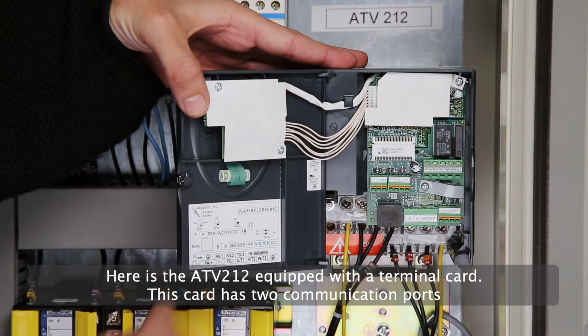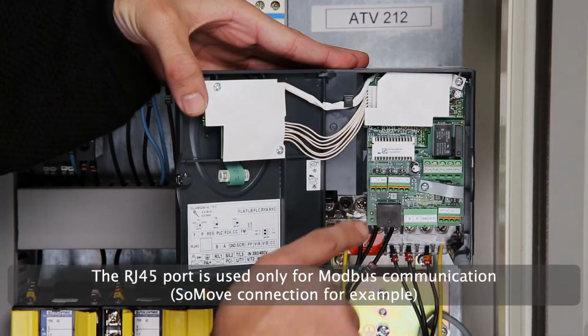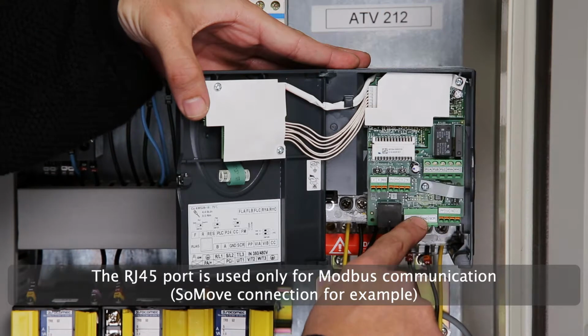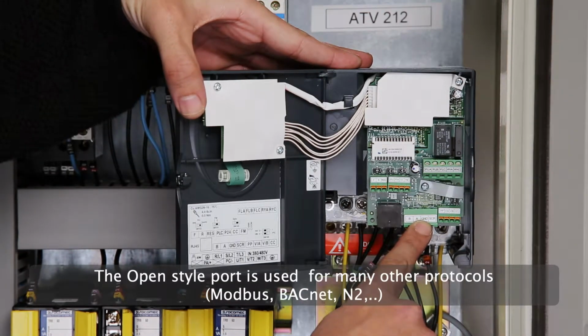Here is the ATV212 equipped with a terminal card. This card has two communication ports. The RJ45 port is used only for Modbus communication, so SoMove connection, for example. The open style port is used for many other protocols.